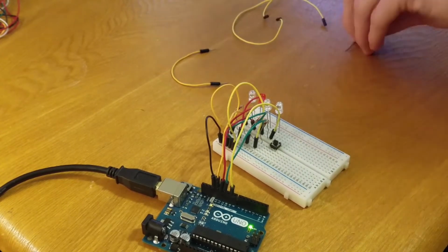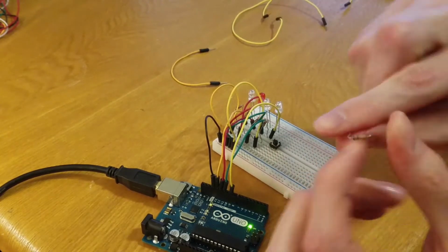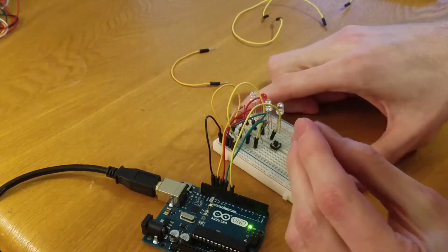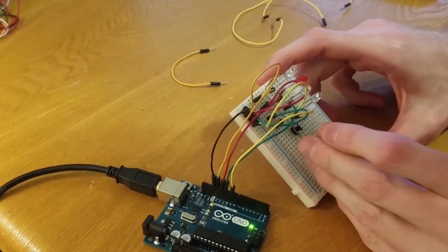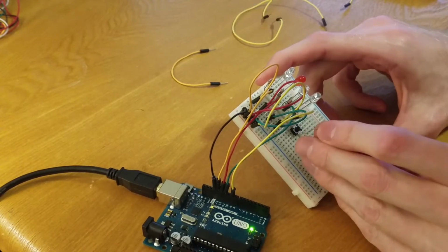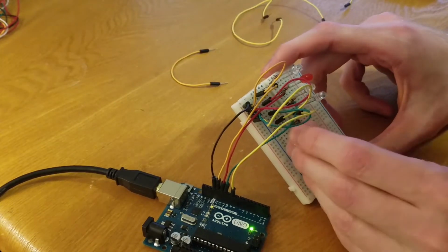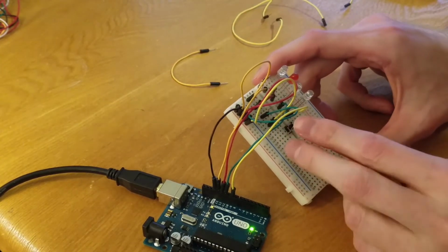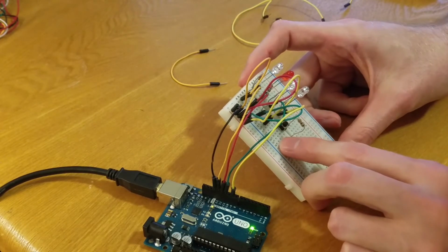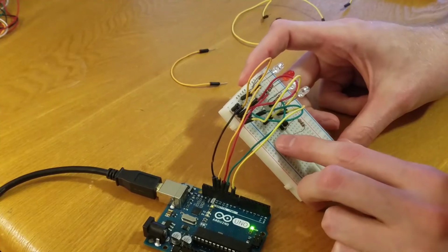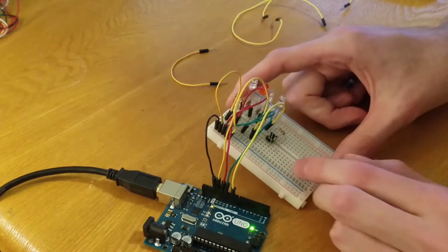All right, let's go ahead and put our resistor in there. The orange is going to go up on my board. The top line of the resistor is going to go to the bottom line of where my button goes to. So we're going to put that right there. And we're going to try to skip just 2 or 3 lines. So 1, 2, 3, 17. So this is on 15 for the top of the resistor, 17 for the bottom of the resistor.